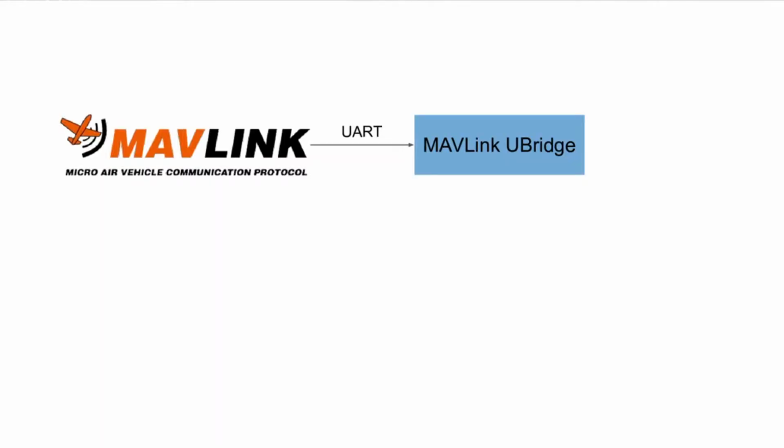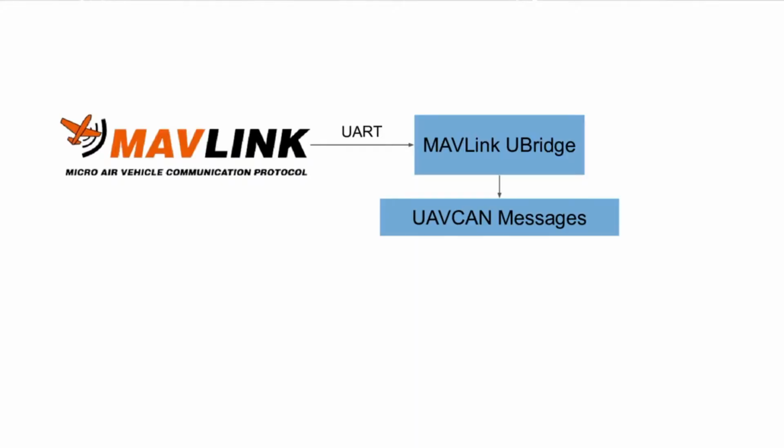To develop the DDS for our ground control stack, we use PyUAVCAN, the reference Python implementation of UAVCAN that allows us to create and interact with nodes very quickly. Specifically, we began development with a bridge node, an application that would serve as the entry point for data published by the drone into the Pilot backbone. The objective of the bridge node is to serve as a broker between the Mavlink communication link to the vehicle and Pilot's internal DDS. We started the development process by writing custom UAVCAN types corresponding to common Mavlink services.